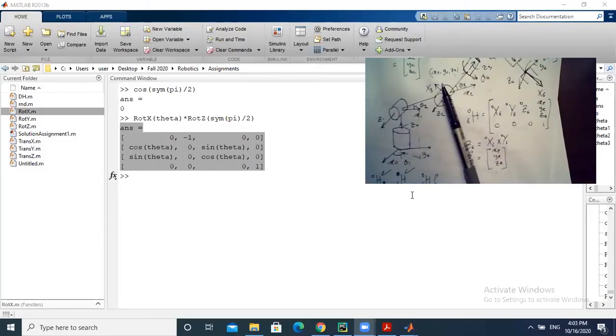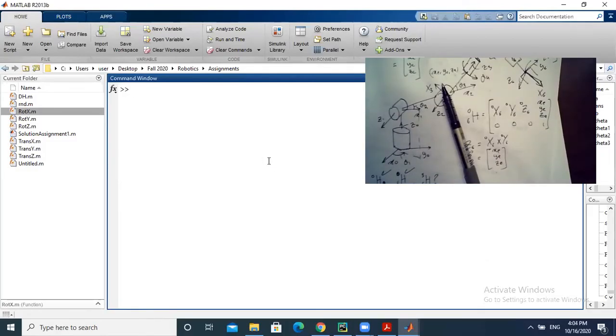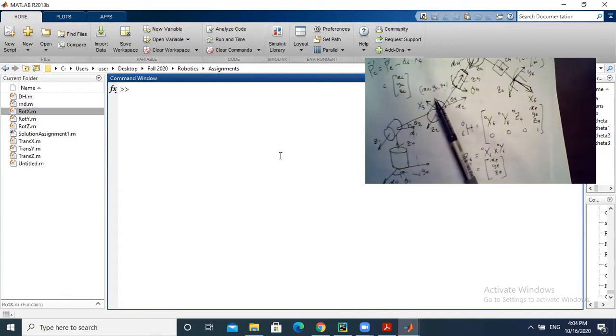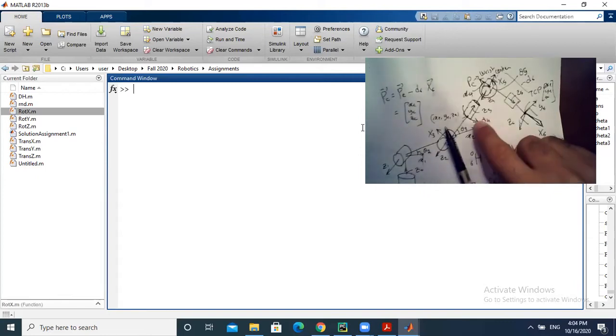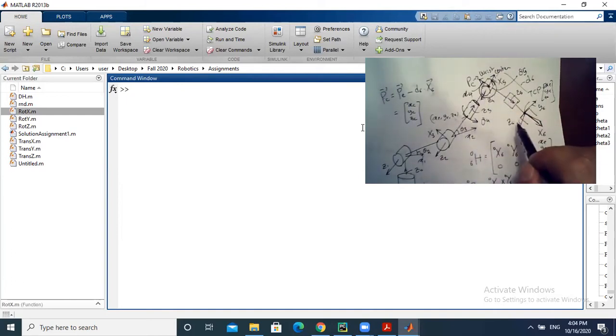Okay. If you look at what is happening here on the end effector, or the wrist kinematics, what do you think we're doing if I want to obtain the transformation between this guy and this guy, or basically frame 3 to frame 6?